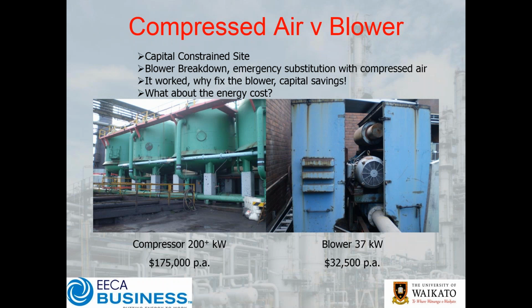The problem is the blower cost about $32,000 per annum to run. The new compressed air solution used over 200 kilowatts of compressed air. It meant an extra compressor was running that wouldn't otherwise have run. And so just in energy cost alone, it was $175,000 per annum. So you can see a substantial increase in the cost of the business, and in fact the energy spend would have paid for a brand new blower in far less than the current operating year.